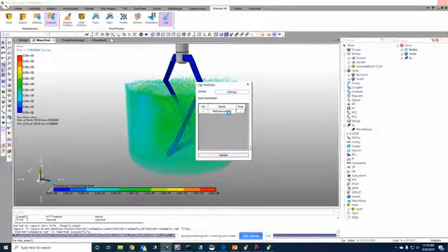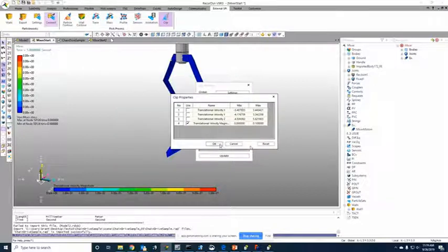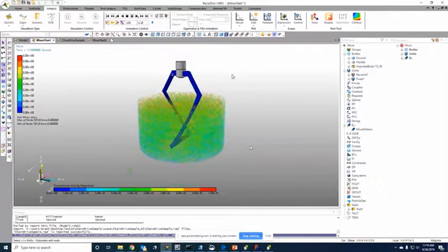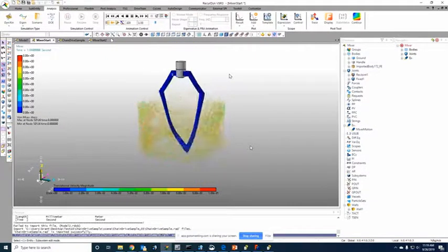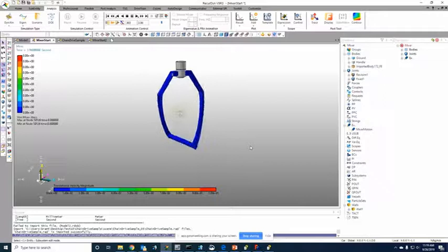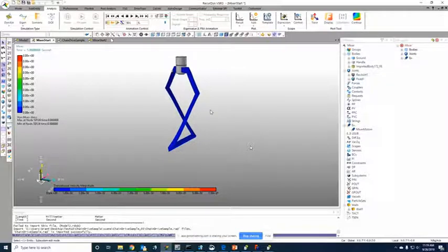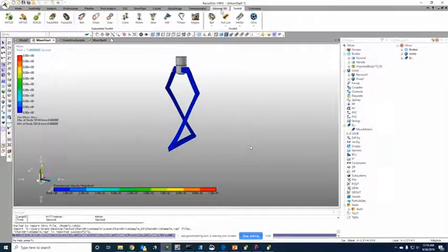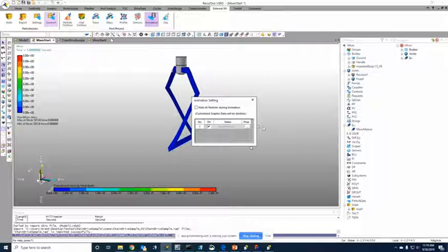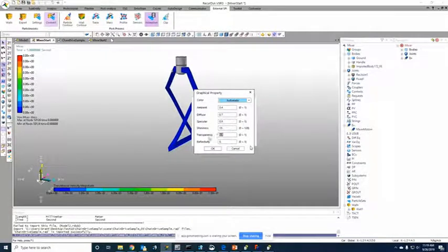And so what I did here is I set this so that there would be a maximum velocity to those particles. Now when I run the simulation, it's only showing the particles that are under a certain velocity. One of the things you might be interested in is certain areas that aren't being accelerated, are at a low velocity, so you can clip the particles in that way. And those are just a few of the different ways of viewing everything when you do receive your results.